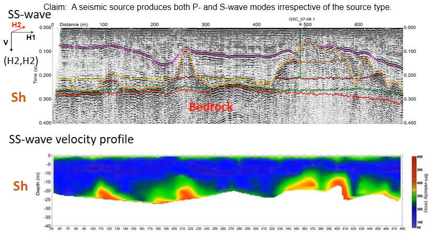The lower unit is a hard limestone bedrock that is not penetrated by shear wave here, as there is too high a velocity contrast between the top sediment and the rock. The mounds are filled with gravel and diamicton, as confirmed with borehole data, and this is a reservoir with an artesian aquifer. Highlighted in yellow, a sand layer is present just over bedrock, and two units of clay separated by an erosion surface are picked in mauve color.